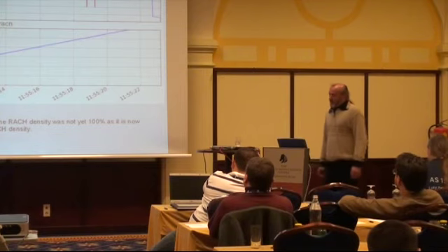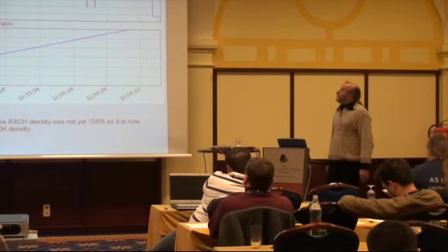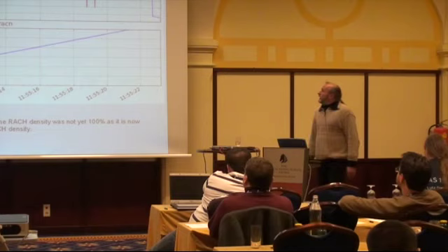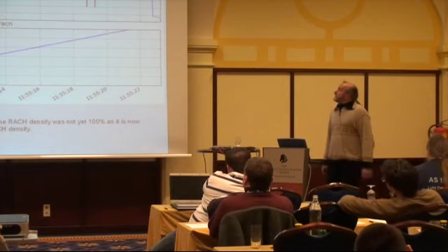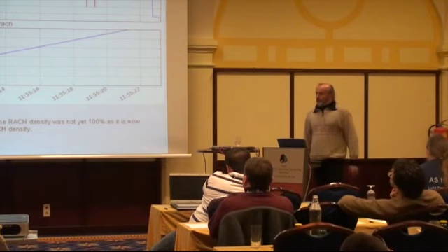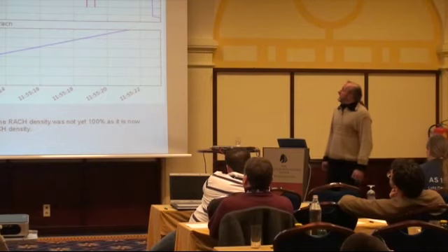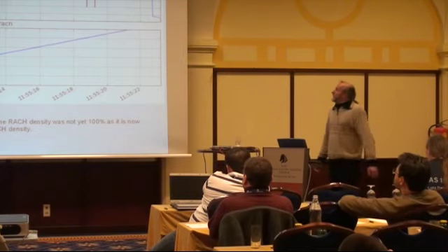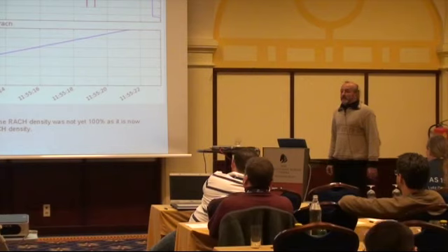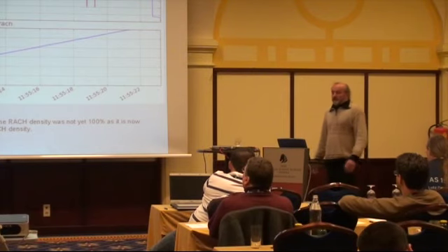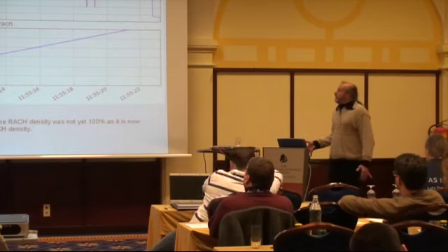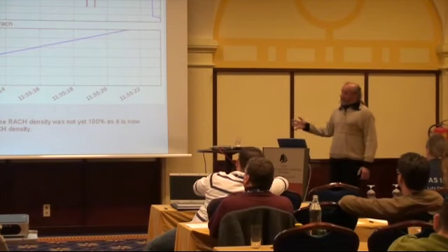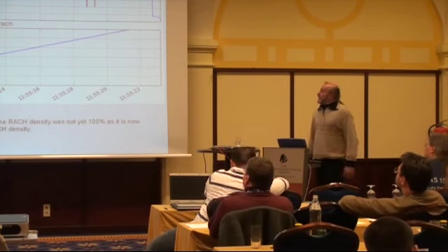From this diagram, we can see one thing. In the case of not jamming, another phone would only have a chance to get a channel in those places where the drops happen. If you look at the red lines, you can see that this error is most certainly rather small compared to the length where all the channels are allocated. So if several phones try to get access in a large cell, they have the chance to get through, but only if they are exactly at that time where channels are already dropped.